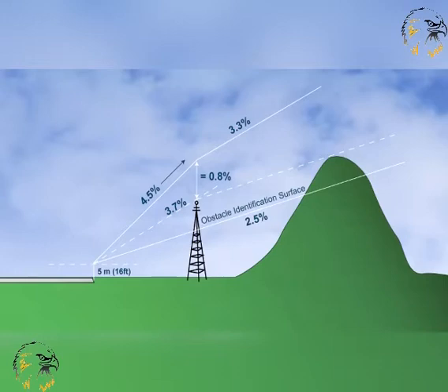The minimum obstacle clearance equals 0 at the departure end of the runway, DER, and thereafter increases by 0.8% of the horizontal distance in the direction of flight, assuming maximum divergence of 15 degrees. If the resultant PDG is too steep, a turning procedure to avoid the obstacle laterally might be the answer. Alternatively, the aerodrome operating minima could be increased until the obstacle can be avoided visually.